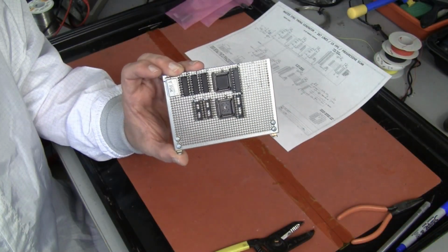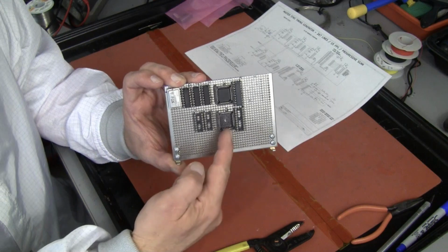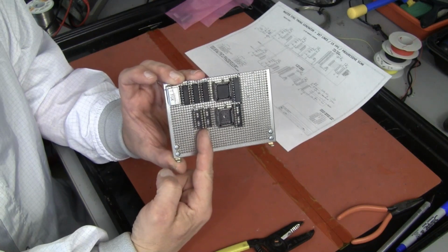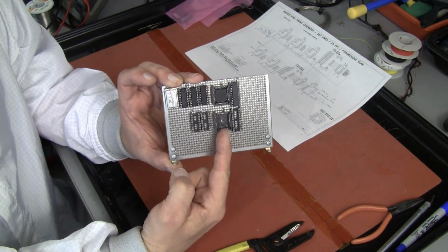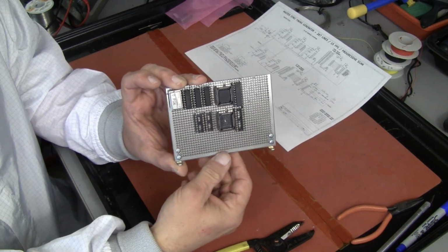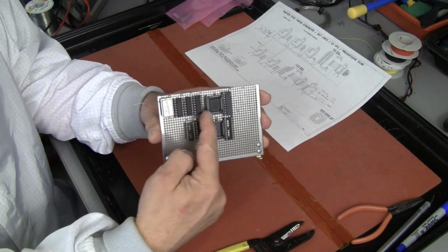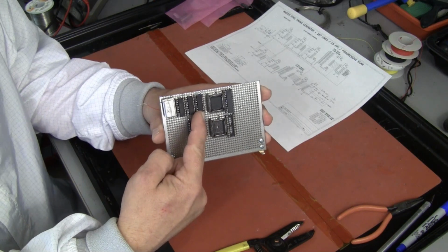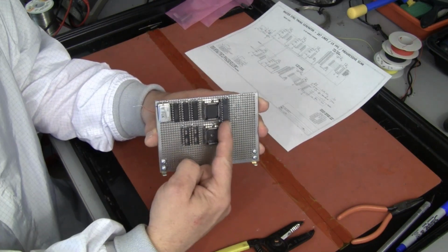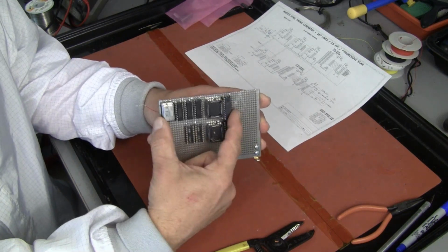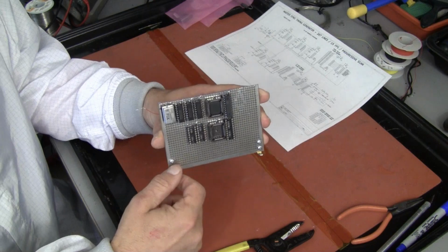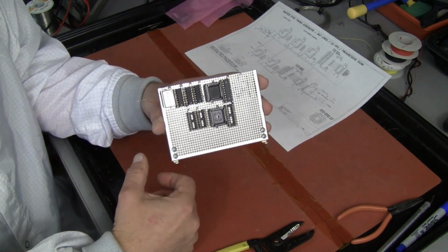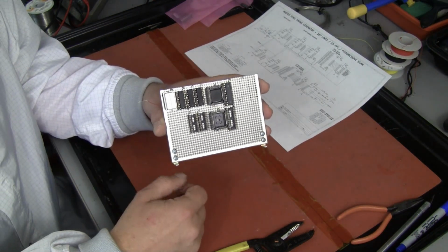Since the last video, I've reworked the board a little. This memory used to be over here, and this latch used to be over here. I've moved them so that I could put in the two new binary counters that drive the image memory chip. That circuit is not wired yet. This is the upper circuit you saw on the schematic here with the master clock oscillator, the three 8-bit counters, the sync memory chip, and the sync pulse latch. This section now operates. So it's able to produce a vertical sync pulse and a horizontal sync pulse at this time. I'm still working on the code to program the remaining bits.